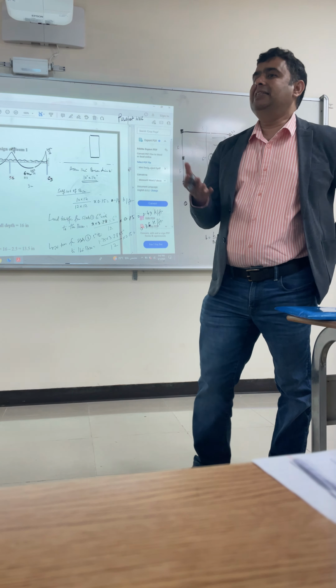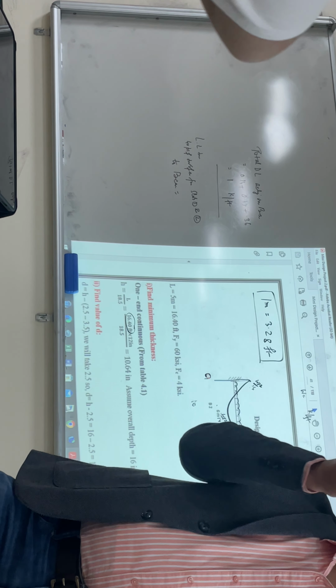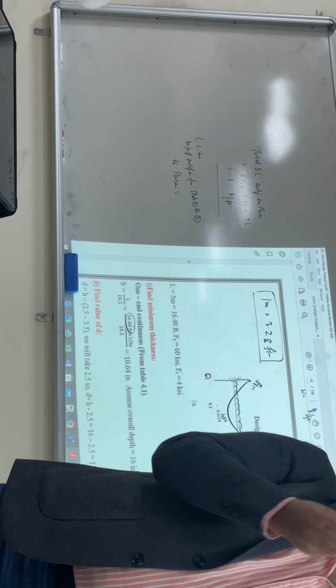Only for the air conditioning, so the live load is basically zero. But it is a roof, so the roof live load is a little bit less than the floor live load, because rarely anybody goes on the roof, maybe for cleaning. Maybe 2% or 3% will go. Everybody will not go to the roof. That is why we are assuming the minimum value of 40. We are assuming 2 kilonewton per meter square for the live load. Clear? Now here is the live load which is acting on the whole slab.